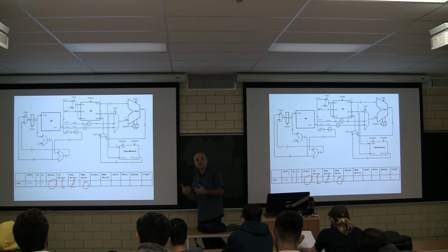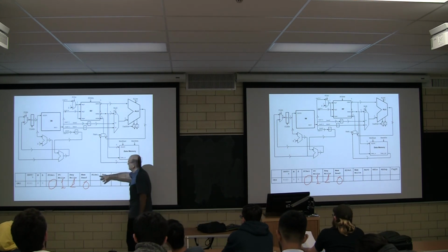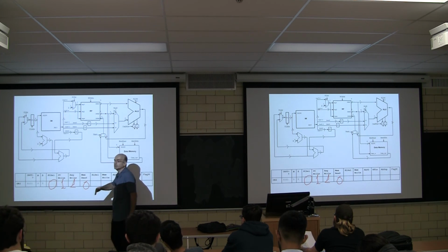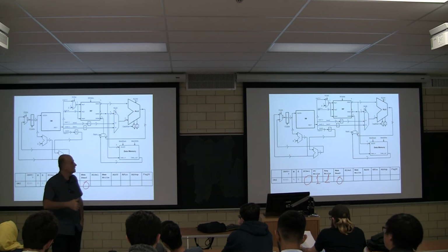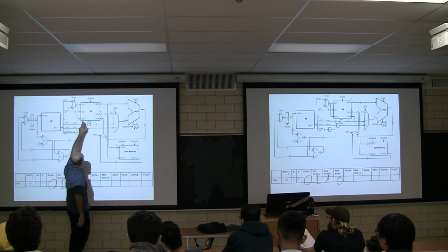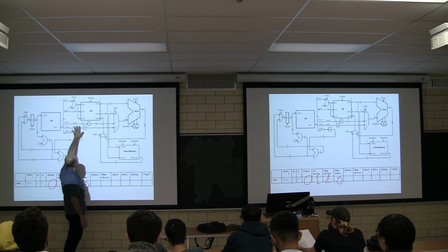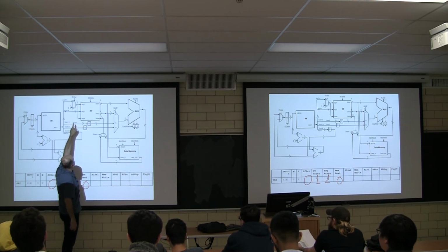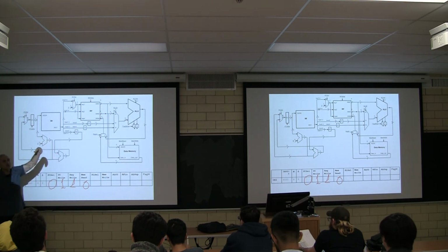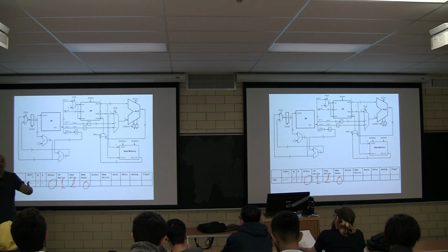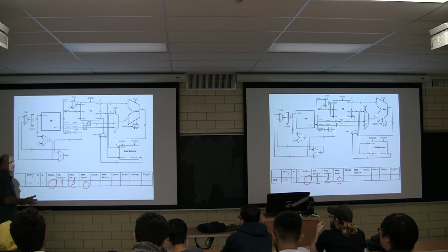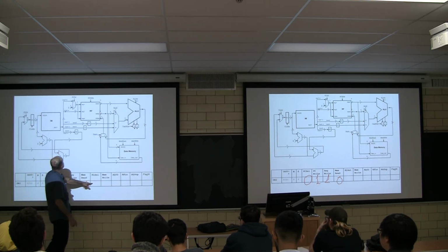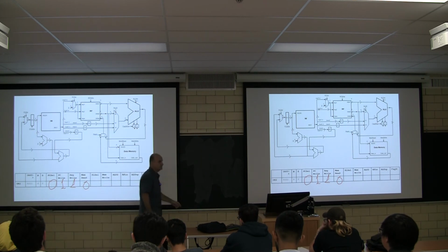And what I mean by that, where should it come from? Should it come... R1 select? Sorry. R1 select is what is the register name we're going to give to the register file as the name of the register to read as part of the first read port, the one on the top here, register 1. It will give you some data, and the name of the register we're going to write. So it controls that multiplexer over here. Should it come from the upper 2 bits of the instruction, or should we force 1 for R1? Again, just to move forward, this is OR-I. We have to force explicitly R1 because that's what the definition is. So this value here has to be 1 according to that diagram. Okay.